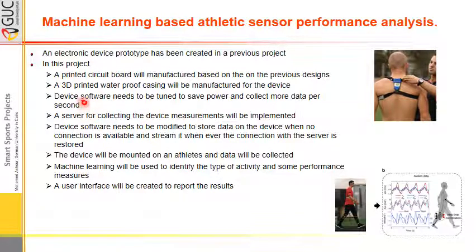And then we need to tune the software of this device so that it is very power efficient and enable it to collect as much data as possible. This data is reported regularly to a server, and the device software needs to be modified to store the data on the device when the connection with the server is lost, and then stream it to the server when the connection is restored.